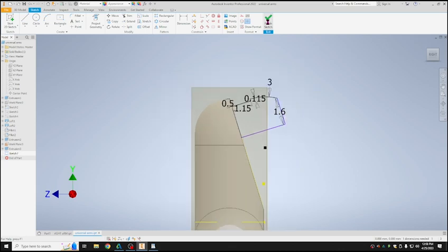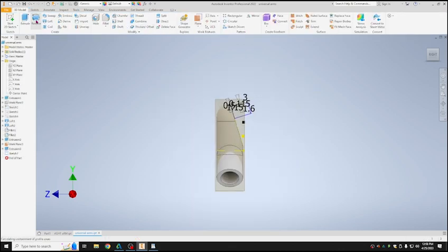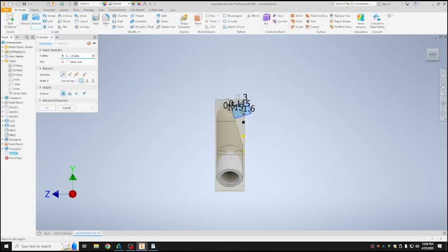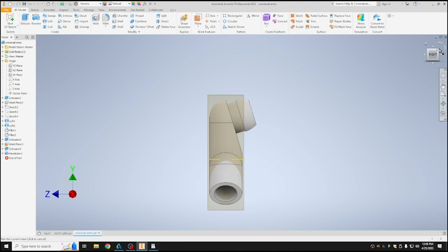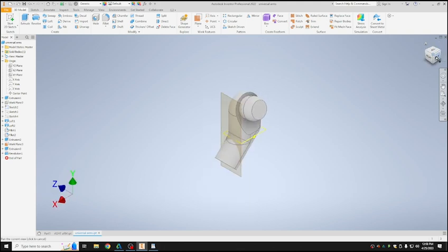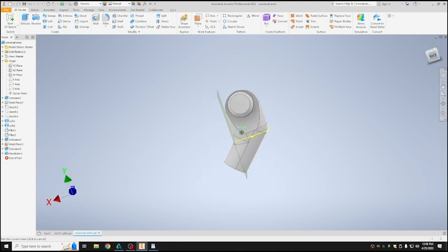We're going to finish that sketch, and now we're going to revolve it. Okay, so you select that object, and our axis is going to be right here. Okay, hit OK, and there we go. We're looking good. All right, so let's go to the last step here. We're going to draw right on this circular surface, so start a new sketch on this surface.